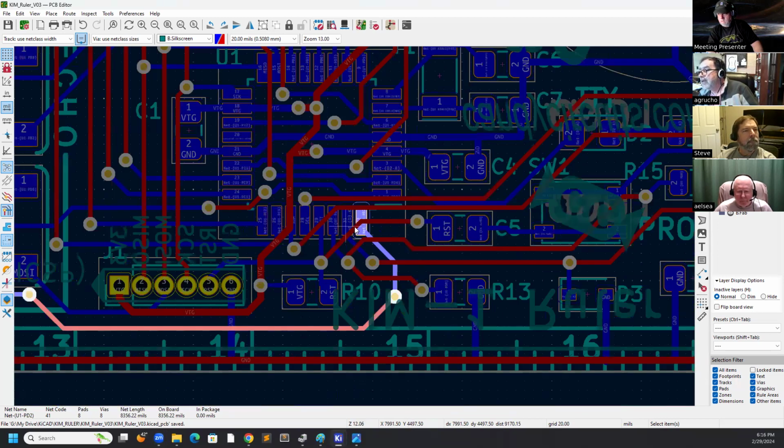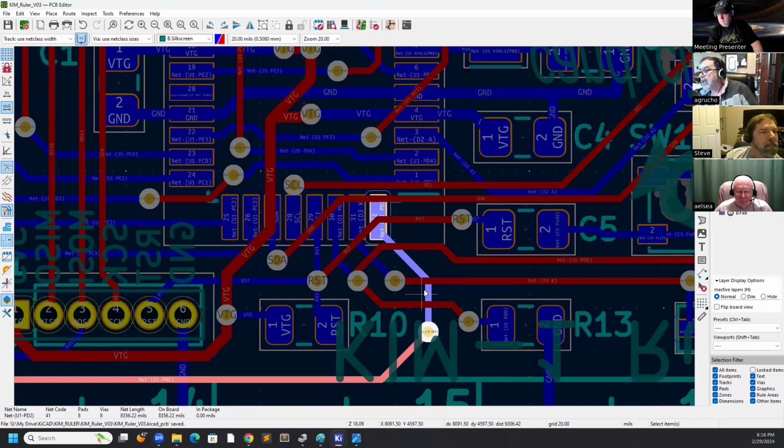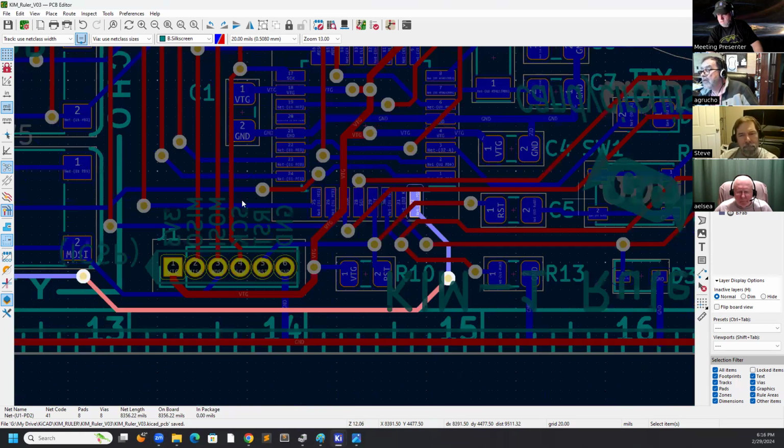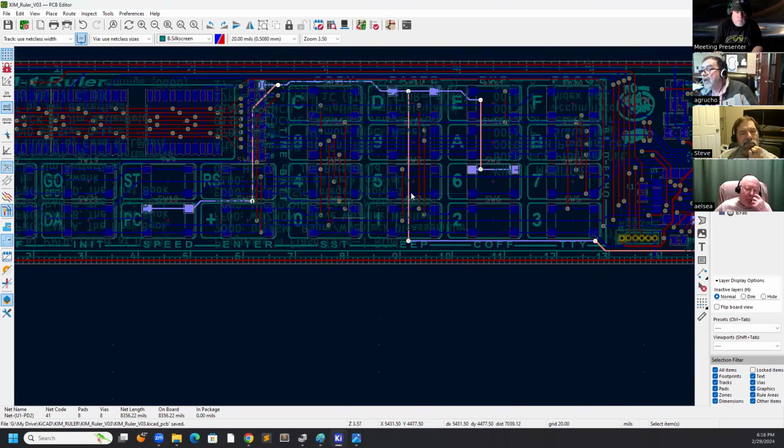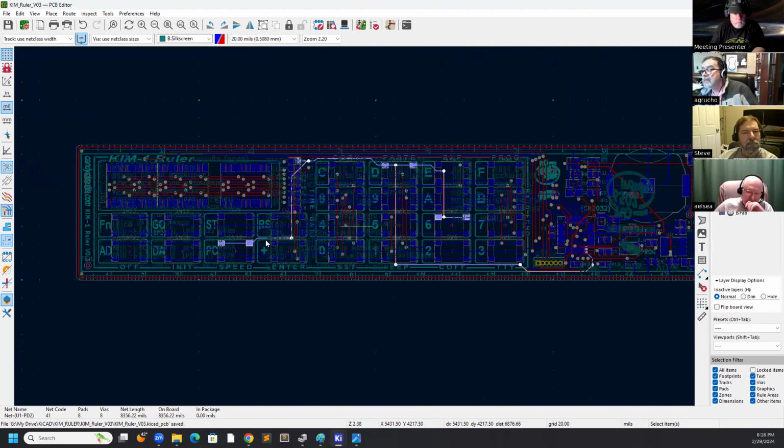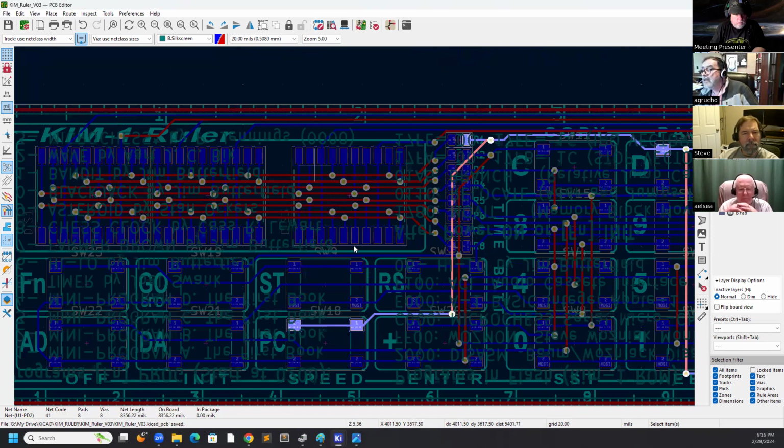You see the path of the microcontroller pass through. You can see the route in the board, how it goes, touching all the points that you need to access. This is the displays. Usually you try to put all the lines in the same direction in one layer and the other direction in the other layer, okay? The difference is here in the displays.